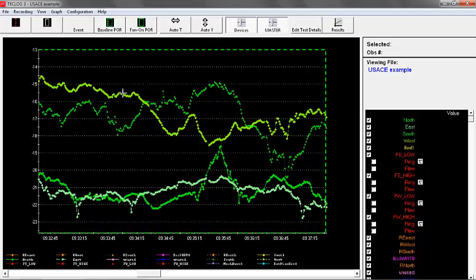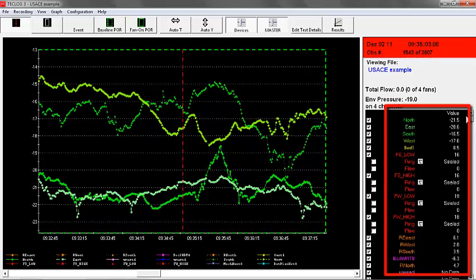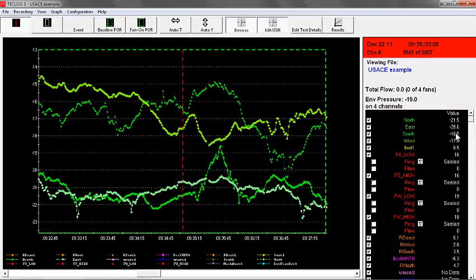But what I'm going to do next is click on this first measurement tool. I'm going to click on that, and that brings a red line here. And at that red line, what'll be displayed is all of the pressures at that point. So our green ones are northeast, west, south, which is what we're seeing on the screen here. We can see the variance in pressures there, and we can see the average pressure. So we can see our average pressure is about 19 pascals.